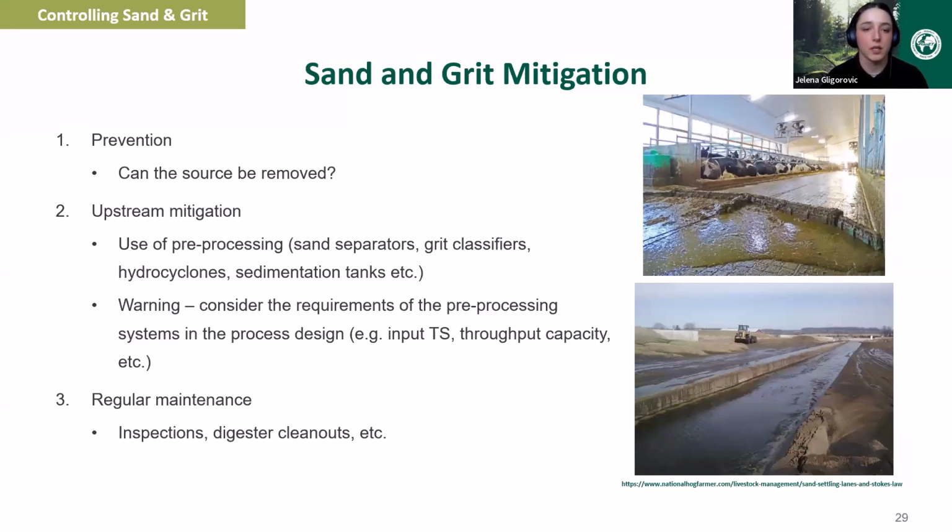So there's always considerations to be made on the actual pre-processing systems that you use as well, and choosing between them. And then the third way of mitigating it is with regular maintenance, so inspections and cleanouts. It can be quite difficult to know if your digester is accumulating sediment unless you notice a reduction in your performance over a longer period of time. So this is why it's important to use data collection to understand the trends and patterns. And if your input stays consistent but your biogas production goes down, that's kind of an indicator that you might need a digester clean out.